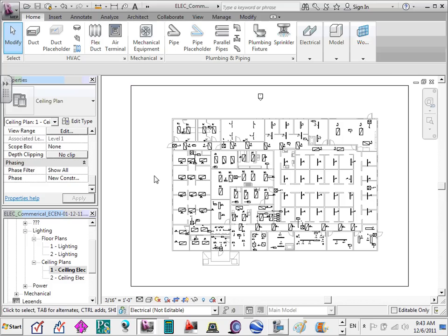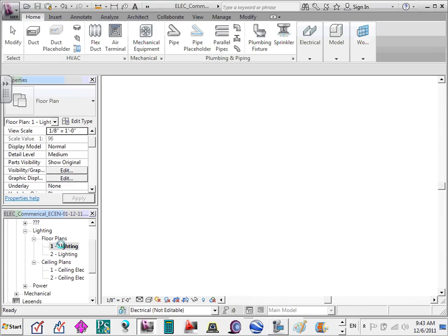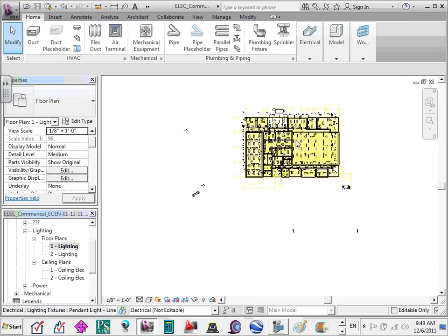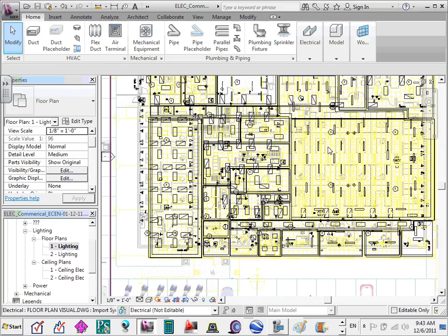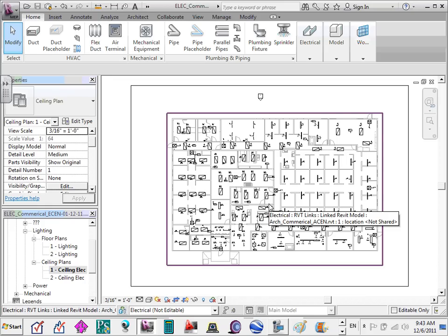But what I want you to know is, we're going to be working with lights. When you work lights, you're going to be in the ceiling. Drop your fixtures in the ceiling. Done. That's what you're going to do. When we circuited in the floor, and we circuited in the ceiling. Look at this, this is an unedited view. This is an ugly view, unedited. I'll show you how to get this one. So what they did, the clean view, as we circuited in, we dropped the fixture in the ceiling and we circuited in the ceiling. When we get into the circuiting and dropping, we'll walk you through. But I want you to know, when you do lights, you're going to be in the ceiling view.